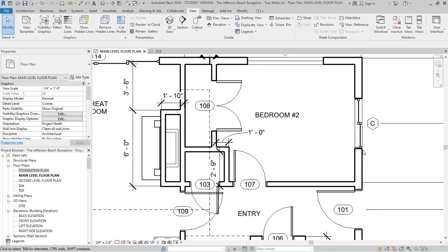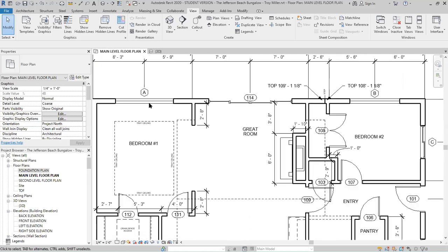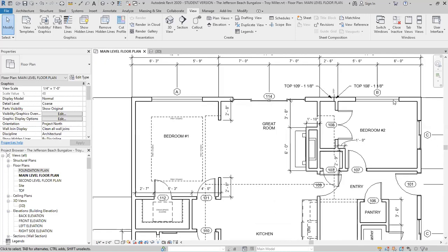And in fact, it's not shown here, but in many cases on architectural floor plan drawings, it'll actually have an arrow showing which panel and which direction that panel would slide. Now, based on an orientation, the panel on the inside of the house would always be the one that would slide, and so it would assume that it would go that direction. But these two windows right here actually are sliding windows too. They have a center fixed pane, and then they have two sliders on each side.